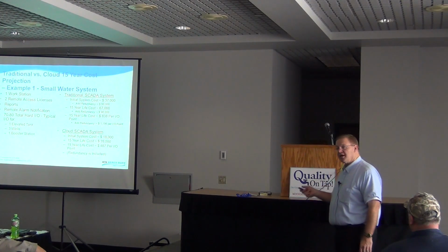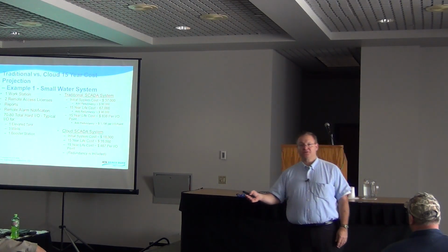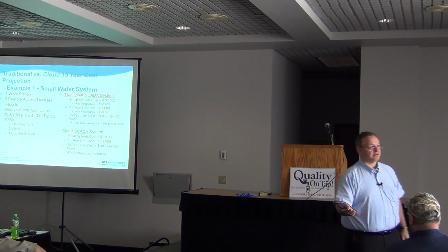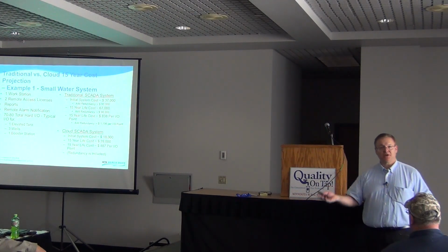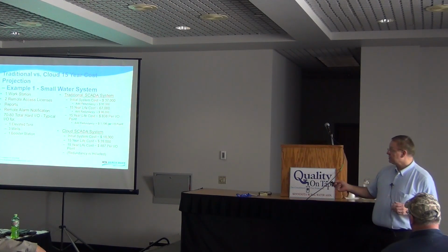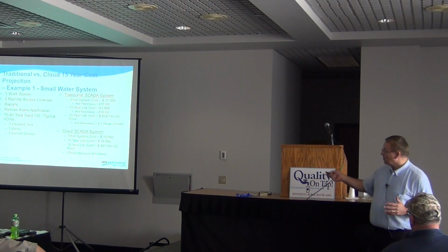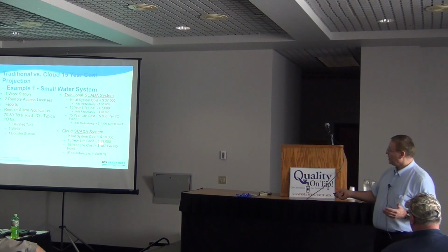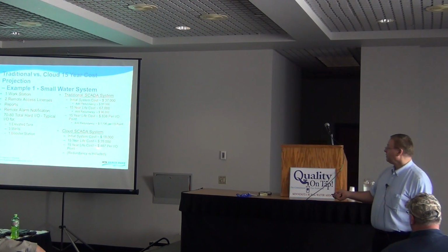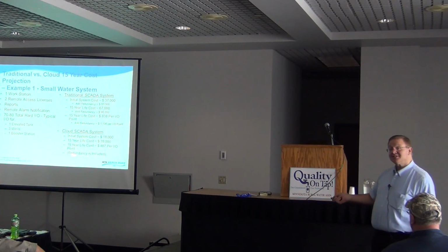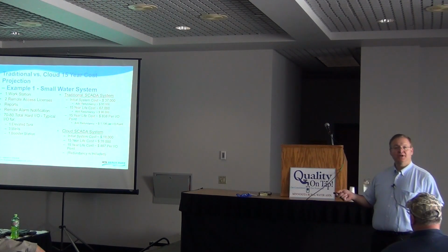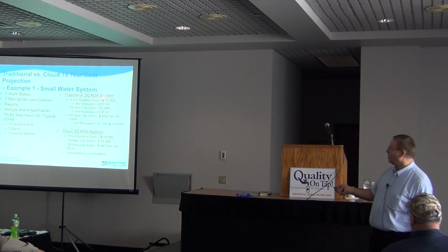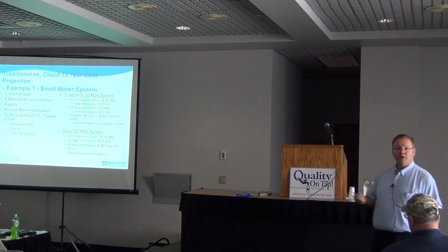Now what gets added into that is there is typically a cost for cloud-based SCADA systems. There's going to be a user fee, and that user fee is typically based on how much data is coming through, but you can still see that it's going to be a lot less than what you would get with a traditional SCADA system. So after 15 years, it's $39,000 rather than $50,000. And the 15-year life cycle is $487 per I/O point, half of it. And redundancy is included. So if you want redundancy, and that was going to be part of your traditional SCADA system, then you're way ahead of the game.